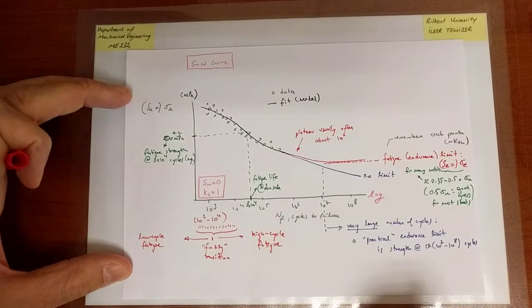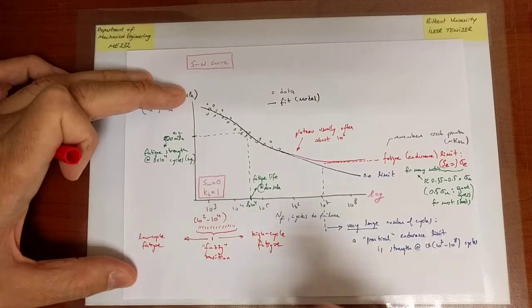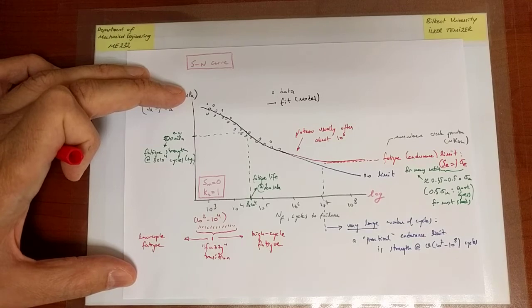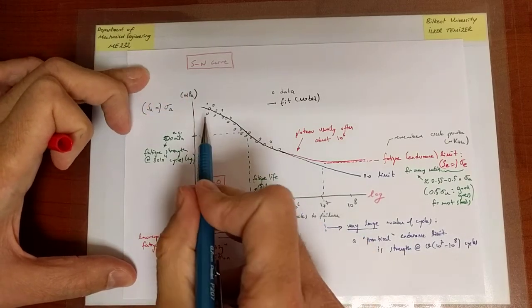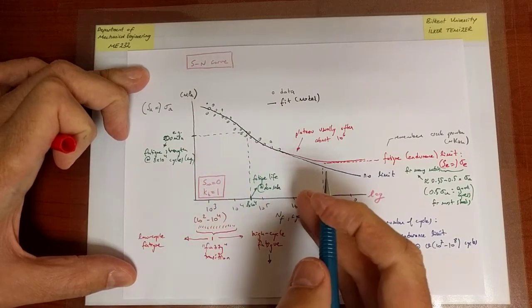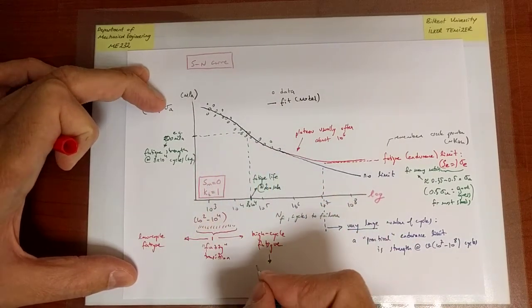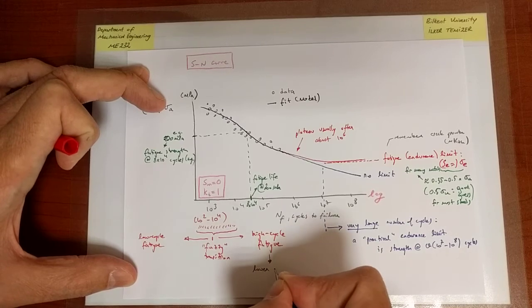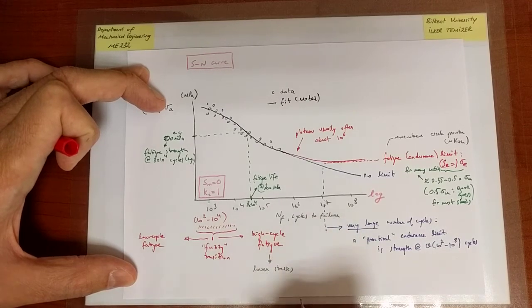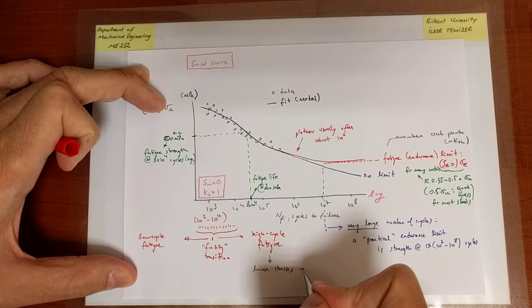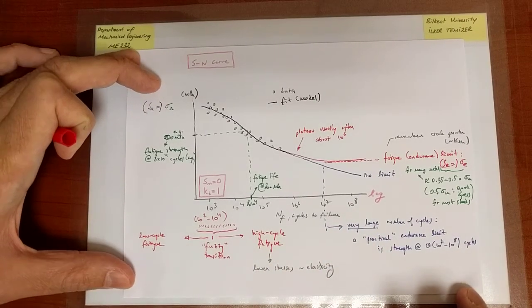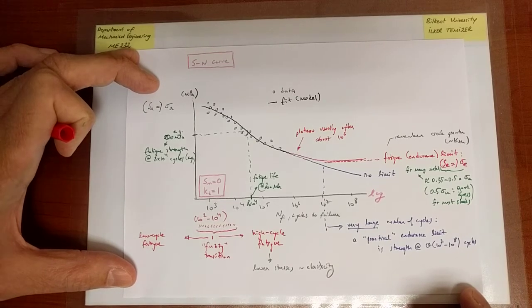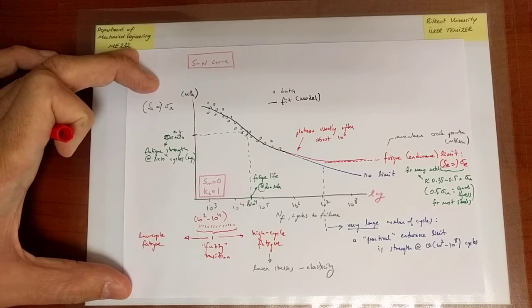Now, high cycle fatigue is characterized by stresses that are, as you see from the plot, lower: if you want to reach higher lives, then you have to decrease the stress amplitude. And when the stresses are low enough, you don't observe significant plasticity, or in fact perhaps there is none. So it's predominantly elasticity that we want to really talk about.